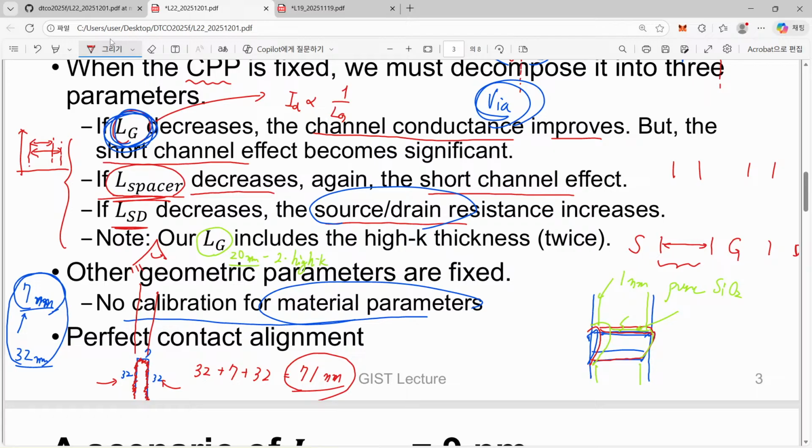That is a really good thing, because we can save our silicon area significantly, but internally we have quite a large area for collecting our electrons or holes. This is the typical way we do it. So if you have, for example, 1 nanoampere as your drain current, then when you report your current, you can just say that per fin, the current is 1 nanoampere.